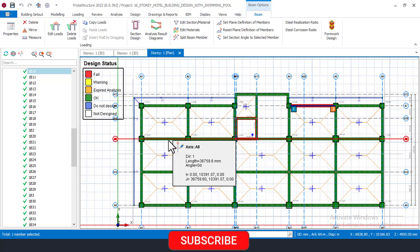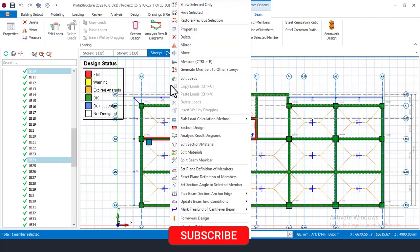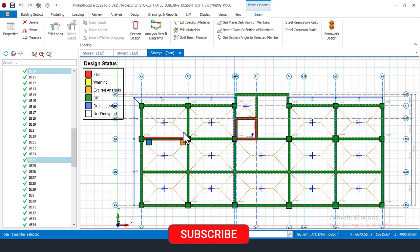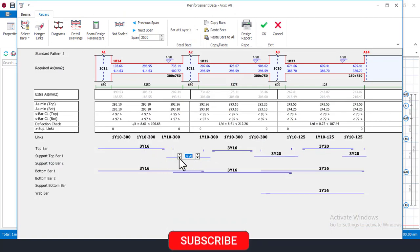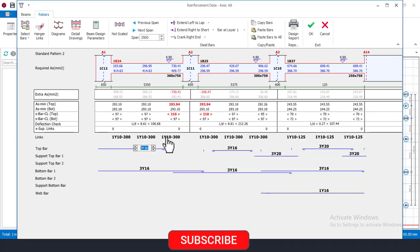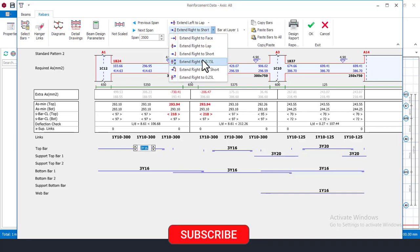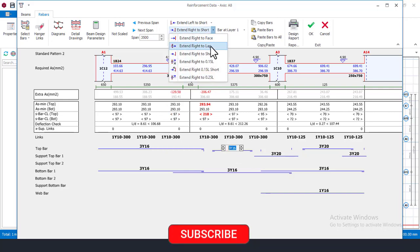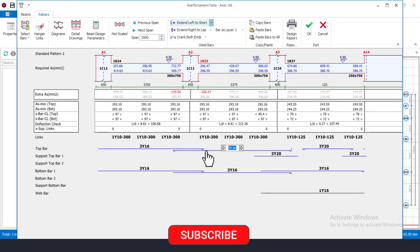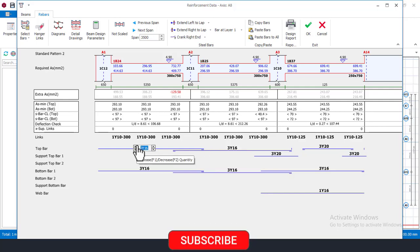Okay. So I'm coming again right now, click on this place here, right click here, and then check this bit again, right click and then check here, and then I will need to check this beam entirely to this very end. So I'll come again right now, begin to arrange my bars here. I can choose to remove this face entirely and see if I can use a lapping bar here to control that failure. Lap into the right, and also here lap left and right, lap, and then towards here lap it too, and try to increase my number to 4 numbers, which is okay, and also here to 4 numbers.